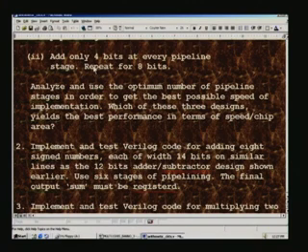From the speed point of view, we are doing this partitioning of the data bus, say 4 bits or 8 bits or 16 bits. So you repeat all this so that you will know where you stand as far as the speed performance is concerned, as well as the chip area, and which of these 3 designs yields the best performance in terms of speed and chip area. That is what I explained just now.